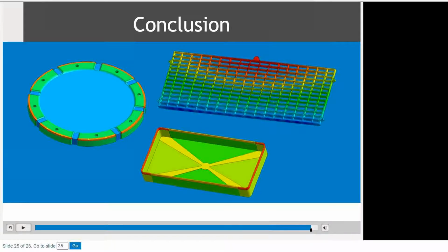So here we have a question from Alex. How do you account for the fill speed affecting how the flow restrictors affect the flow? So basically, do fill speeds really affect the fill behavior even with the restrictors? And the answer is absolutely. Yeah, and this is very key.